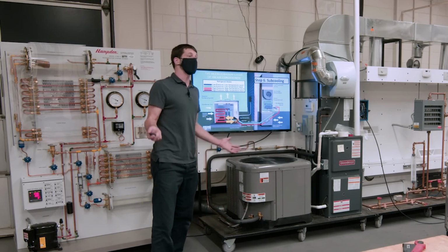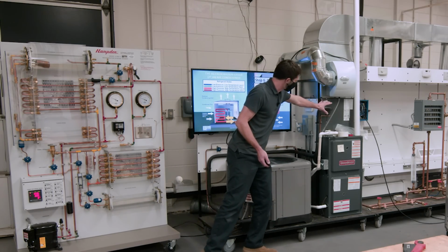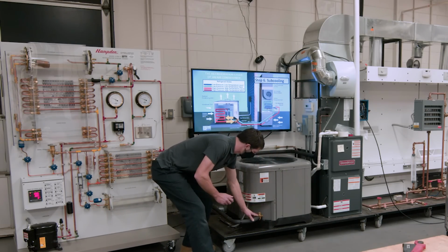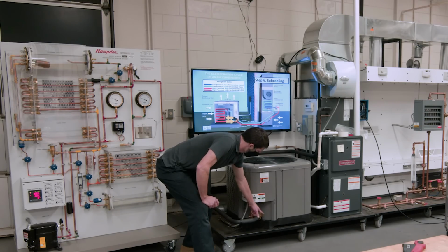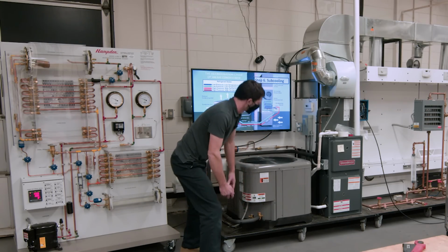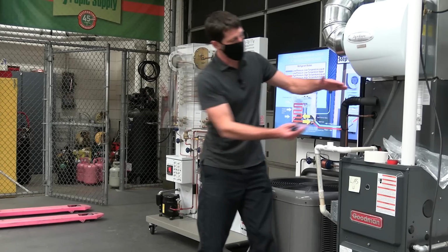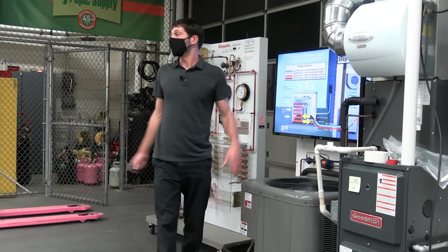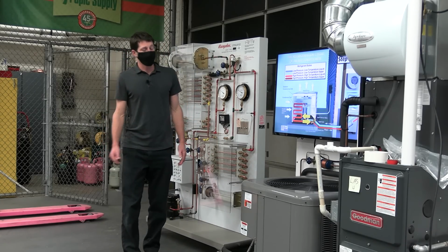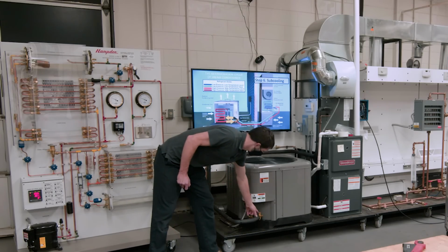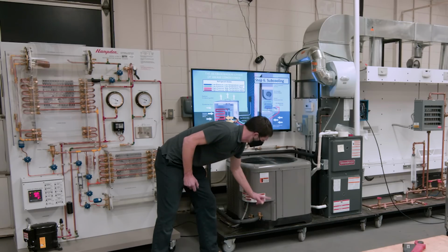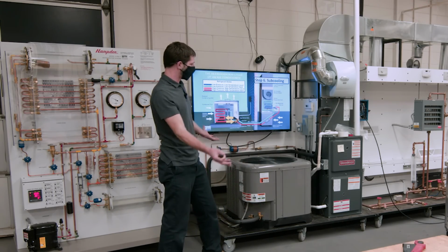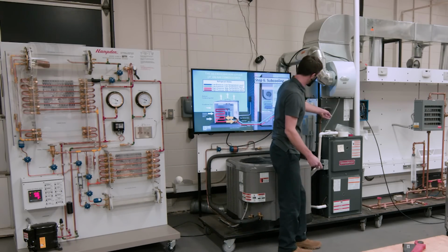So really, even though you measure your pressure here, you're measuring your saturated temperature in the middle of this outdoor coil. It gets even stranger when you talk about the evaporator coil, because when you're measuring your pressure on the low pressure side, you're measuring your pressure here and converting it to saturated temperature. And really, you're trying to figure out what the temperature is in the middle of this coil all the way over here, maybe 50 feet away, 75 feet away. And so then you take a line temperature here, and the line temperature is going to be higher than your saturated temperature here. That's called your total superheat.